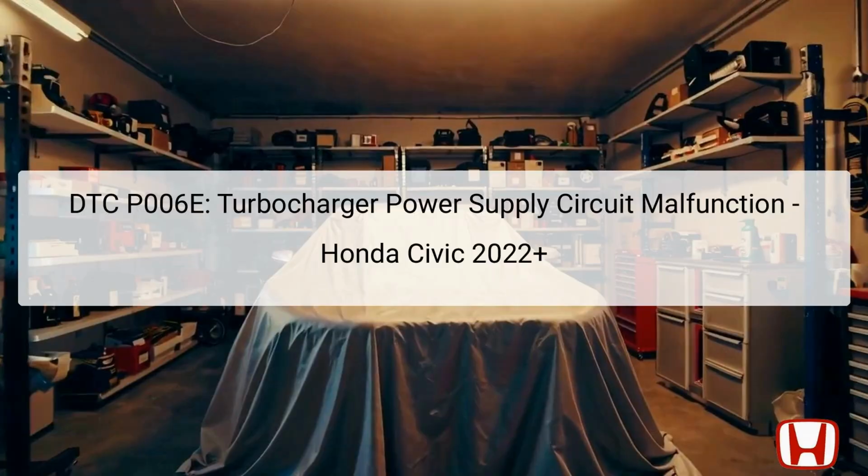The DTC P006E indicates a malfunction in the turbocharger power supply circuit, specifically within the wastegate control actuator system of the 2022 and newer Honda Civic. This trouble code is set when the powertrain control module, PCM, registers an abnormal voltage in the power supply circuit, meaning that the voltage drops below a specified threshold.